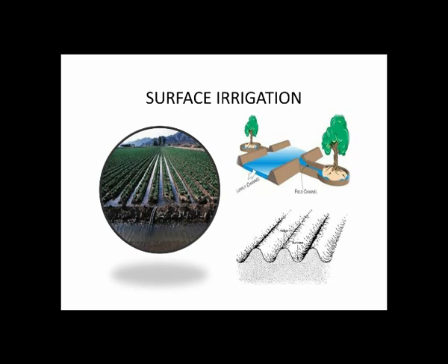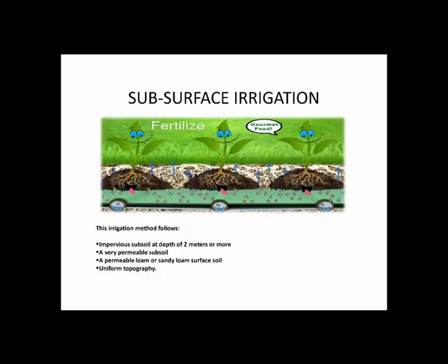Now let's discuss another 2 methods of irrigation. These are basin method and furrow method. Basin irrigation is one of the oldest methods of irrigation and is widely practiced where rice is irrigated. However, furrow method of irrigation is an alternative to flooding the entire land surface. It is about constructing small channels along the primary direction of the movement of water and letting the water flow through these channels which are termed furrows, creases or corrugations. Till now, we discussed surface type of irrigation.